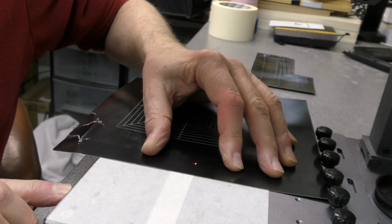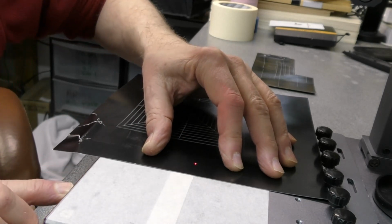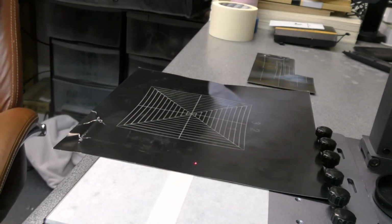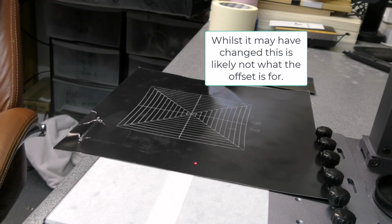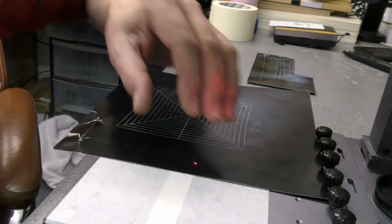So if we bring that back in, yeah, the main laser is just slightly off to the minus, and we're just going to bring up that F3 menu and go back to red, and it has changed it. So it was on 0700, I'm going to put it on 0350 and click OK. We'll see if that moves.